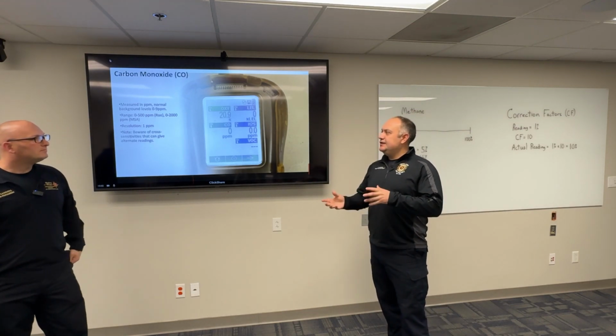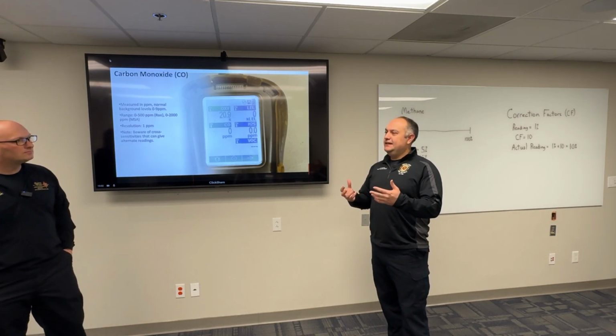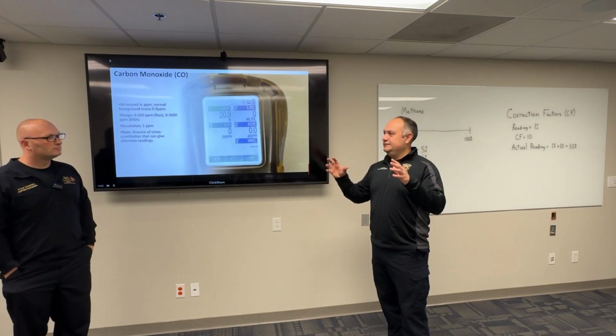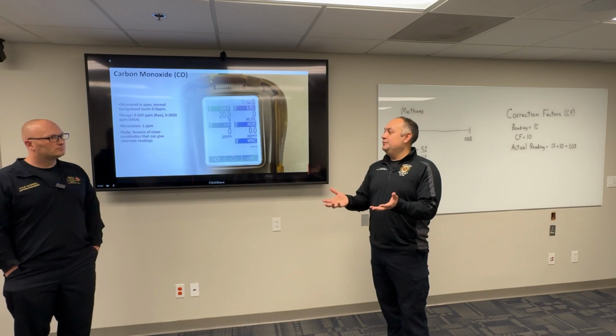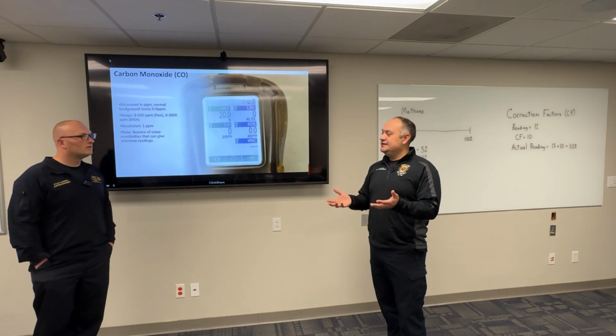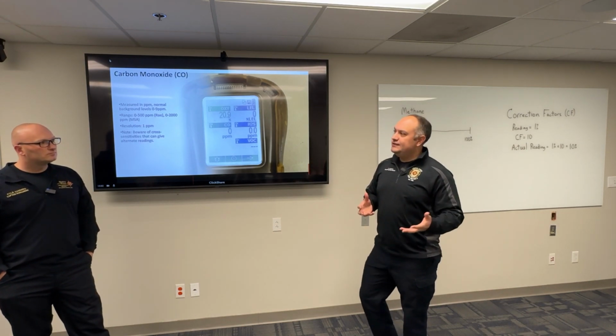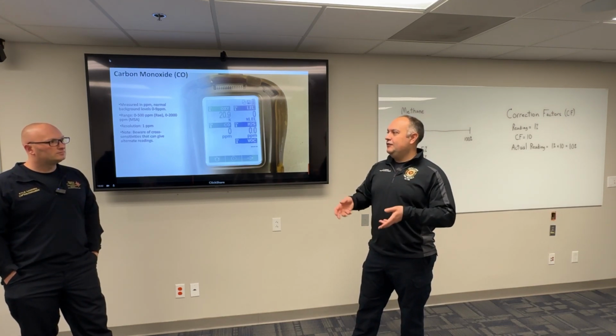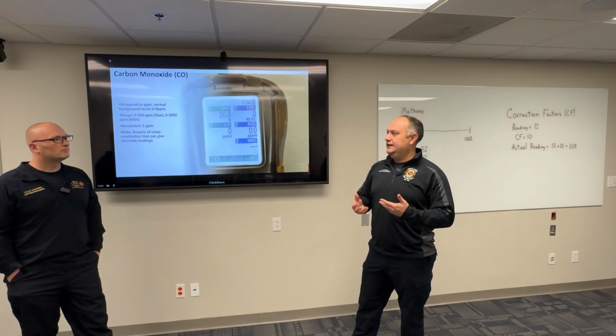So I believe cross sensitivity is when, let's say, a sensor thinks it sees CO, but in Ray's case, there's a bunch of hydrogen in the atmosphere for some reason. We've had that from batteries cooking off, car batteries that sit on a charger, and they give off hydrogen gas sometimes when they overcook.